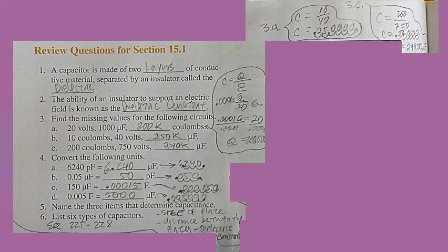Again, you have to move the decimal point to the left, since we're talking about microfarads. We have to basically make it into farads, converting whatever value they give us, whether it's micro, pico, or kilo. We have to convert that into single units, which are farads in this case. So we have 0.0001 equals Q divided by 20.